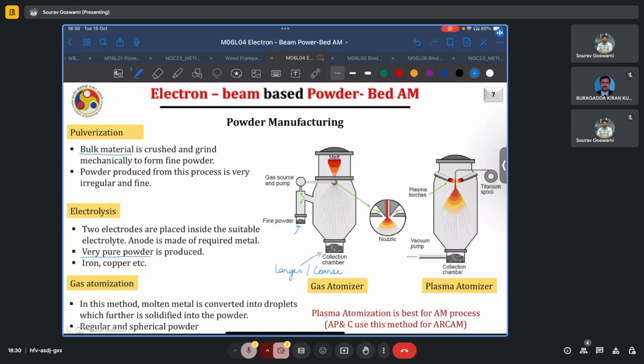However, since this process utilizes some gas, whether nitrogen, argon, or any other, the particles made from this process are also susceptible to gas intake, and thus the final chemistry of the metallic powder will reflect the gas used for atomization and will be different from the nominal alloy composition. In the case of plasma atomization, however, the molten metal is subjected to a sudden vacuum, and because of being exposed to this vacuum, the melt disintegrates into small droplets, which then solidify.